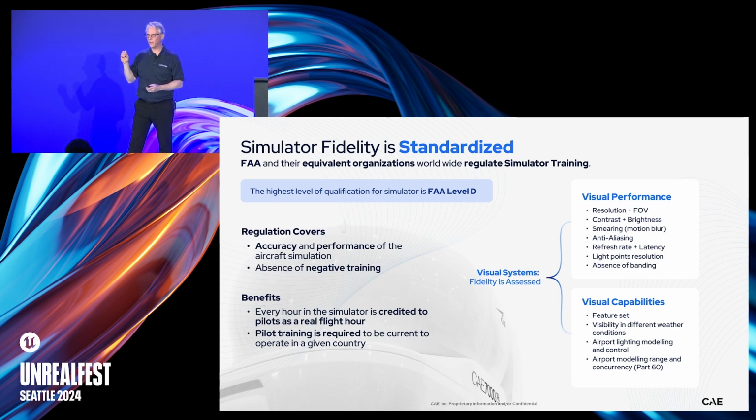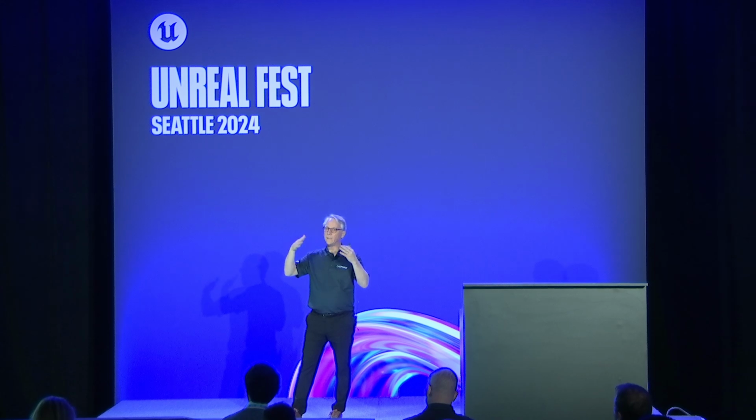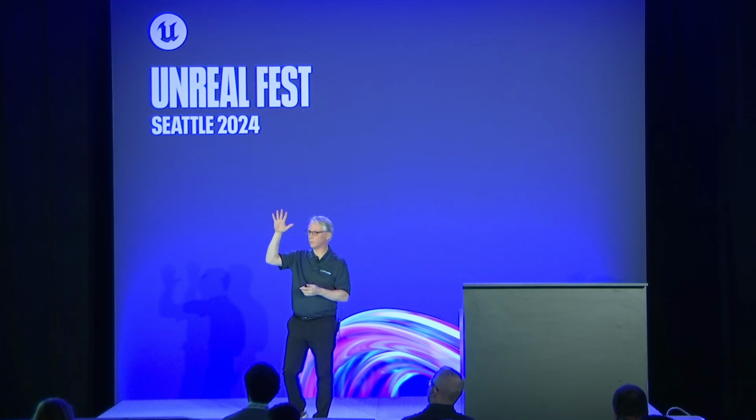And interestingly enough, a few years back, the regulations have added additional training. One of those is what's called UPRT, so Upset Prevention Recovery Training. It's a sequence of events that leads to a very bad situation for the airplane, essentially when the airplane would get outside of its flight envelope. The flight envelope is the range of degrees and speed in which the airplane flies well. One of the typical ones is if you don't go fast enough, you don't have the aerodynamics, so the plane starts to fall, and that's called a stall condition, right? That's a classic one.